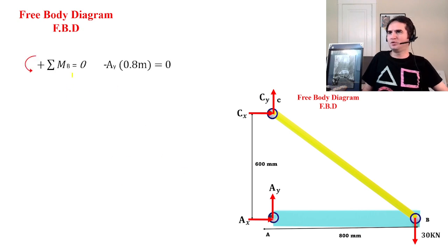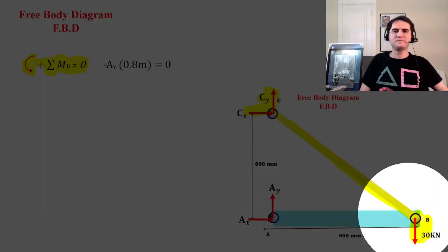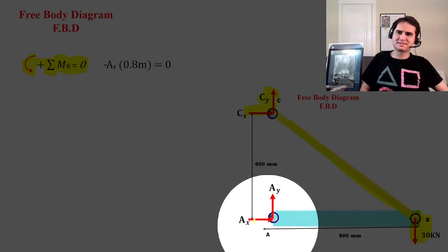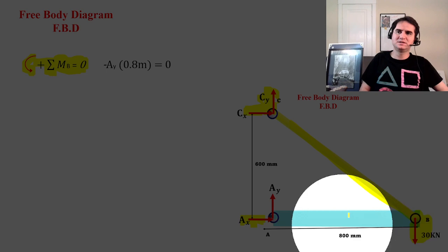And if we develop another moment, about point B, the summation of moments about B goes to 0 this time. It is because the force of the rod, all these components, translate to a resultant force along bar BC, and as you can see, they pass through pin B, so they exert no moment about B. The same story for Ax: it passes through B, so no moment.